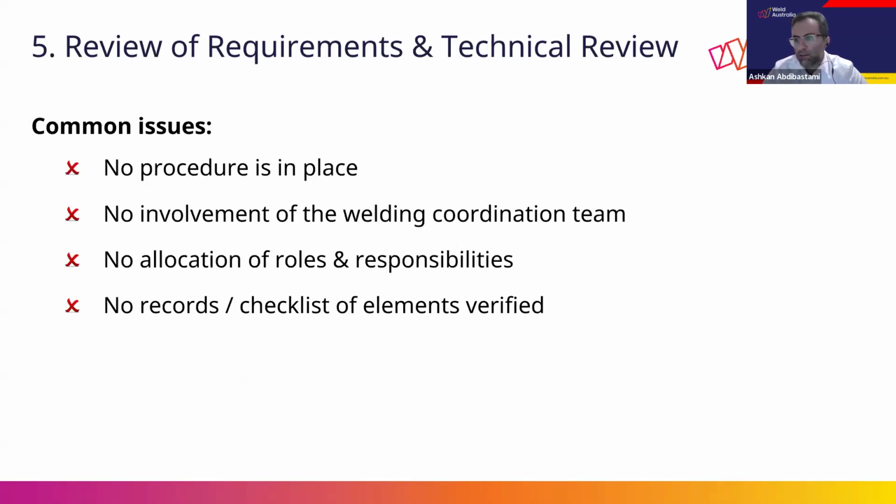I have listed some common issues in each clause. When we go through each clause, I will present some common issues that I came across during the audits. Here in review of requirements, common issues include having no documented procedure, no involvement from the welding coordination team, unclear roles and responsibilities, and missing records or checklists to show what was reviewed.